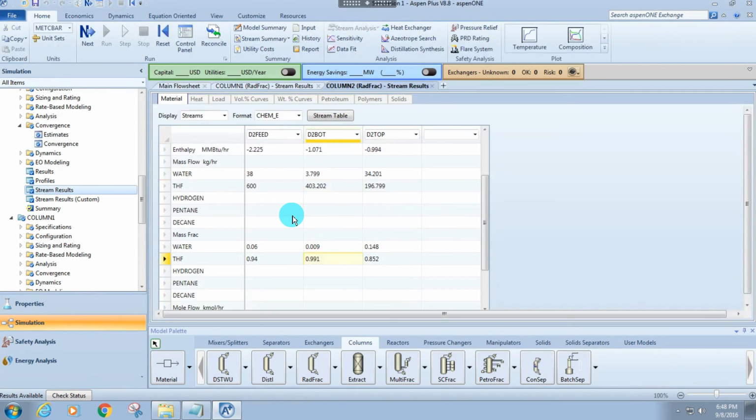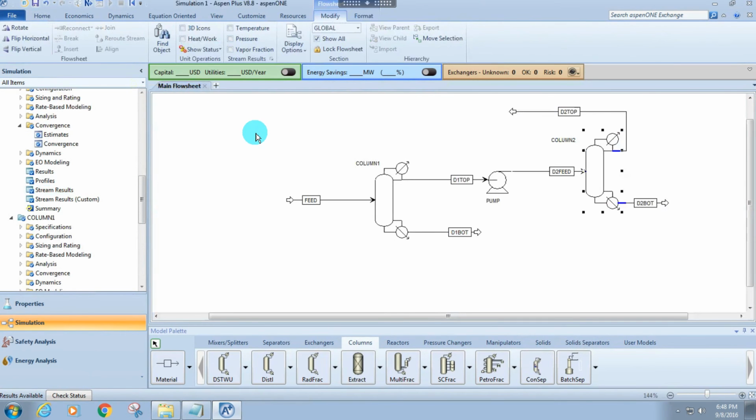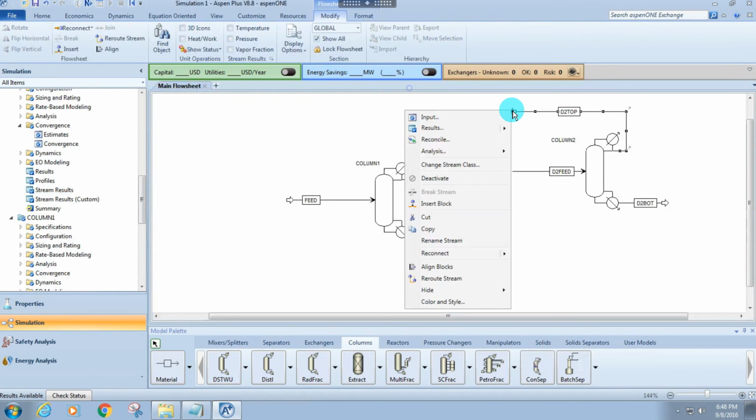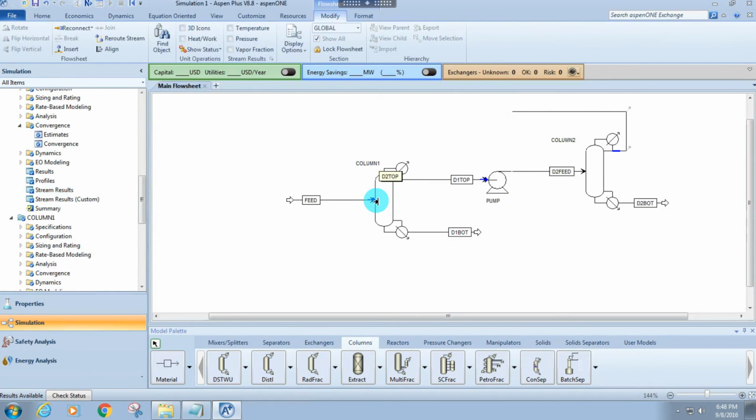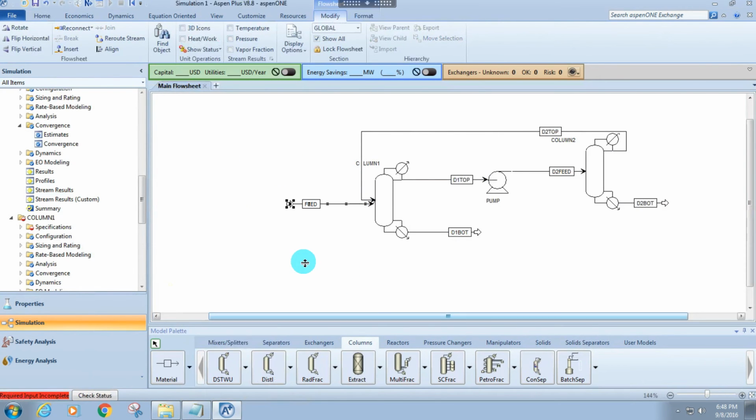So the solution to this, the real complete schematic for a pressure swing distillation, is to recover the lost stream by recycling it to the first column, okay? Now, I'm not gonna add it in here, but remember that our second column is at 15 and it's at 1 here.